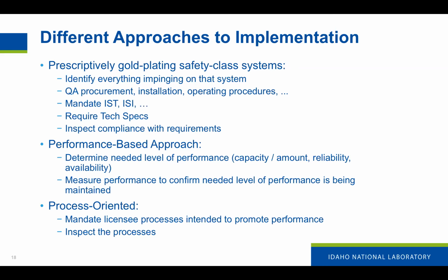So measure performance to confirm needed level of performance is being maintained on an ongoing basis. So things like containment leak rate testing are an example of that, but so is just starting pumps once in a while to make sure they still work, and that sort of thing.